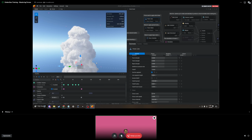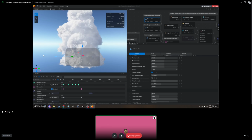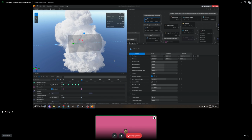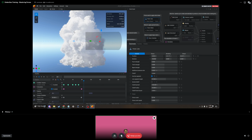You can also do a line segment, which basically means that within a certain length, so within this cylinder of our line force, that's where the line force would be applied, instead of infinitely across the entirety of the simulation, which is pretty cool. So say, for instance, if we had this cloud, but maybe there's a very specific force only in that one little area. Say if we wanted to get a bulge on the cloud, so maybe we'll move this over so it doesn't hit the bounds. We just want to push this smoke over and maybe get a bigger bulge on this side to artistically direct how our cloud is growing or whatever it happens to be.